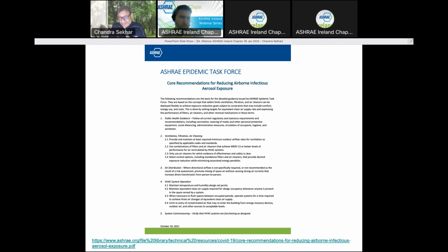So this is interesting, what we now have in terms of the core recommendation you see here, compared to what even ASHRAE and REHVA said back in early 2020. At that time, we did not know too much about SARS-CoV-2, so we were erring on the conservative side, if you like. We said let's not recirculate because we know the virus is likely in the room air. And we said let's not even do anything to reduce the ventilation, so don't do demand control ventilation.